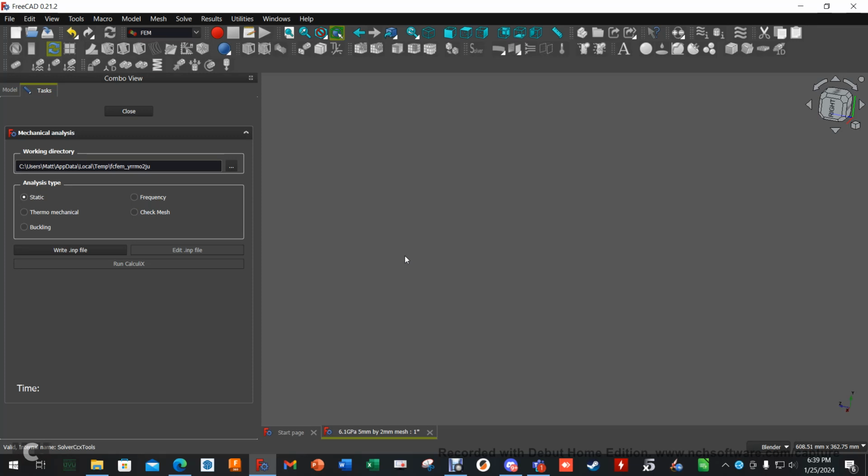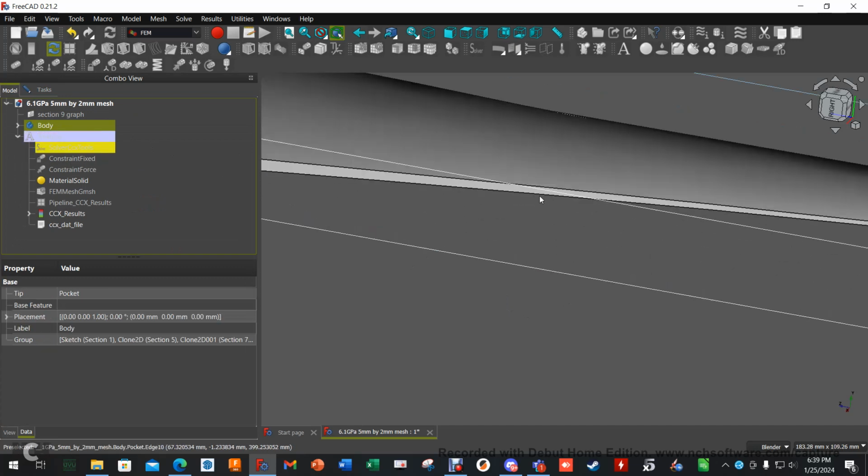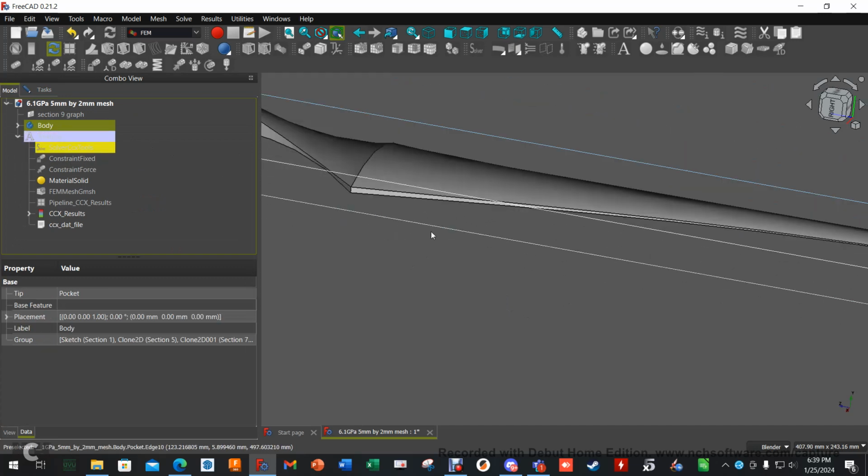And then from those numbers, we can input them into other simulators and get fatigue life. We could use an open source program called OpenFAST and MLife and get fatigue values back. And then we could also use OpenFOAM to do CFD, and in that case we need the other model that doesn't have the flat edges, that has the actual airfoil, because this would be a terrible airfoil.